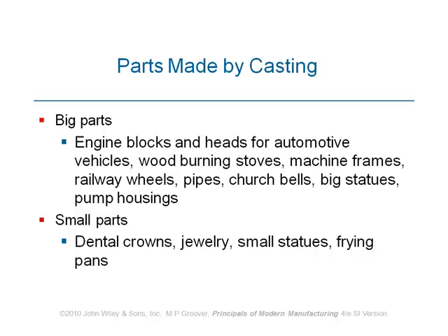I'm aware that when engine blocks are put together, they actually make the engine block out of aluminium, and it's extruded aluminium. It's not cast, it's extruded. Well, extruded aluminium, you mean it is injected into a mold? Well, it is still in the category of casting processes. It's a permanent casting process, die casting, where you make the cavity and inject the molten material into the cavity. So when it is cooled down, it takes the final shape of the cavity.